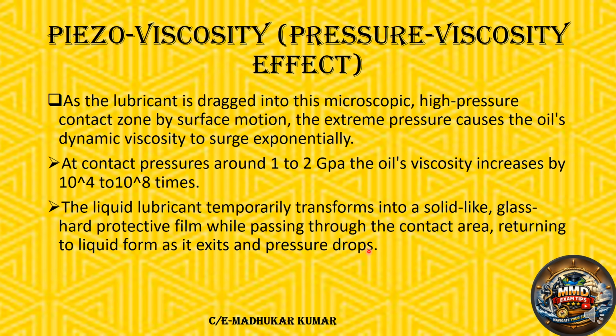The pressure at contact points is around 1 to 2 gigapascal, and the dynamic viscosity also changes 10 to the power 4 to 10 to the power 8 times. So you can imagine the situation. Due to this only, elastohydrodynamic lubrication exists. And once the oil returns to the normal liquid form as it exits that part, the pressure also drops. So this is very interesting to understand, the piezo viscosity effect in elastohydrodynamic lubrication.